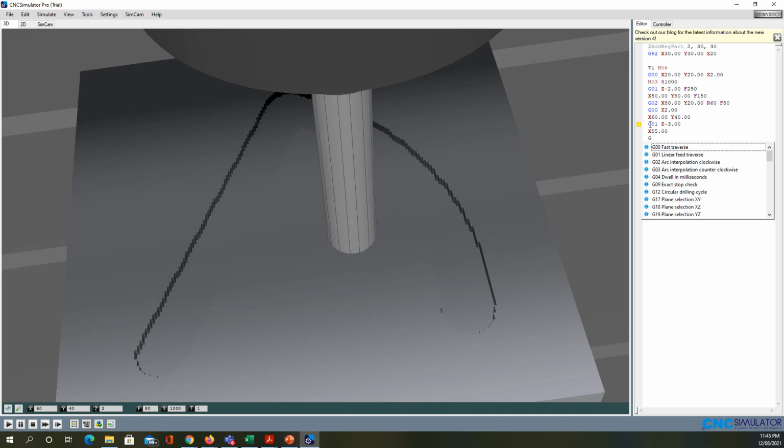And then I'm going to do the G03, and make the location back to the point where X is equal to 55 and Y is equal to 40. I just try to do a full circle. And the I is going to be equal to, in that case, X 60, Y 40. I hope it's going to work this time. I, J, 40. Now let's give it a try.